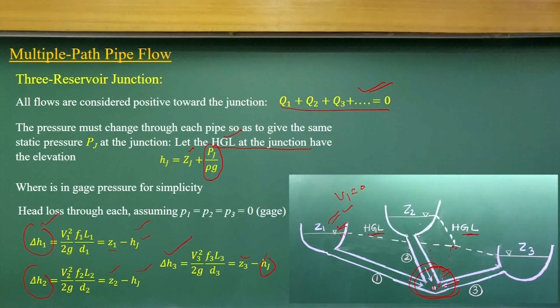So, how much energy loss will happen determines the hydraulic gradient at the junction. That is what we apply with the losses to compute what the head losses should be in this direction, this direction and this direction. Based on that we can compute the flow contributions in the Q1, Q2 and Q3 directions.